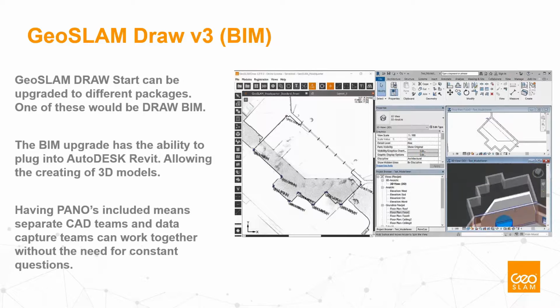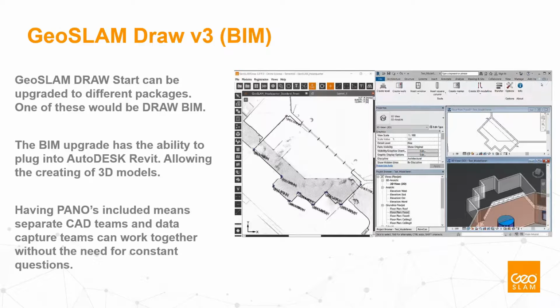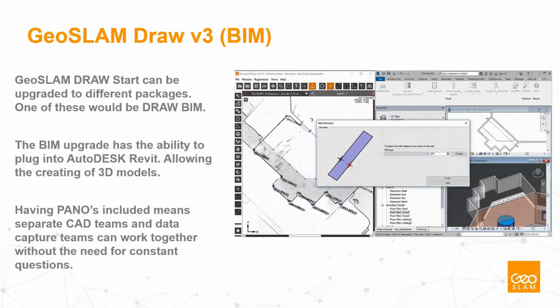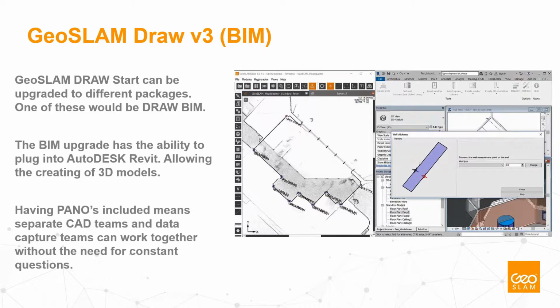So if you're able to have a small point cloud, the LAZ, and also a very small file size, which would be the 360 panos, send all that out to the person that is creating these 3D models. They can then use that extra information to really understand what is in the point cloud. So clicking on the 360 panos, looking at what's in the space and making sure that the 3D model is representative of what's really in that space.